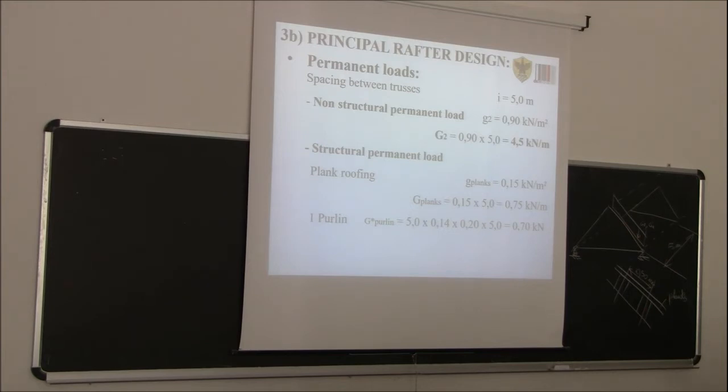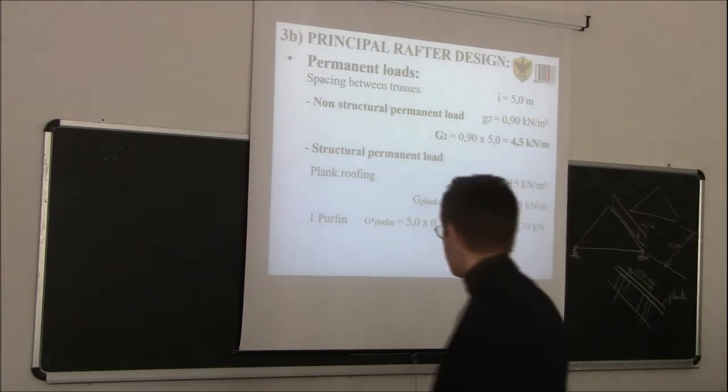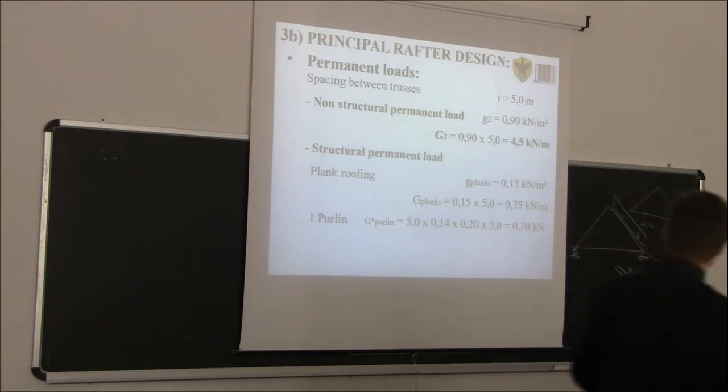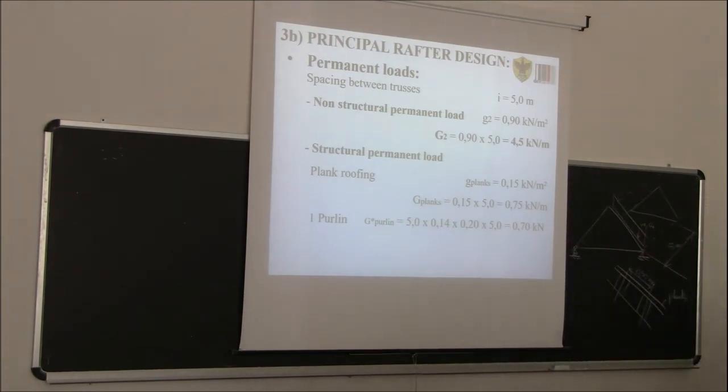So how can we transform, I mean, strictly speaking, those purlins, what kind of load would they apply on this truss? If we wanted to be rigorous, so if you wanted to speak with someone from mechanics of structures, what would you say? What kind of load condition would we have here, strictly speaking? We would have some point loads. Because you see, all the loads above coming from the roof is actually transmitted to the post here, to this rafter, through the purlins.